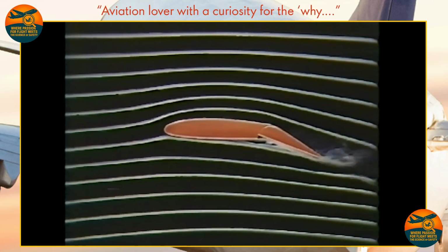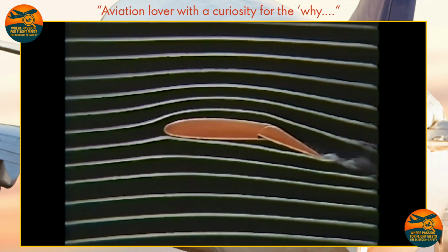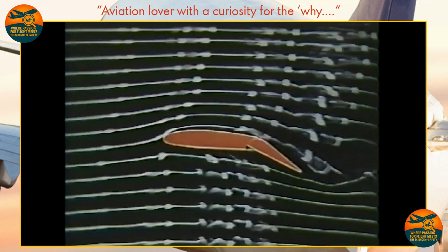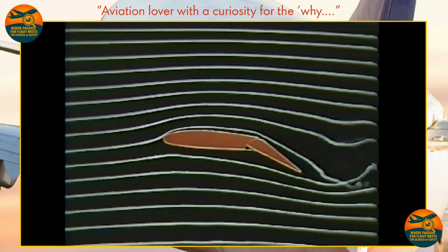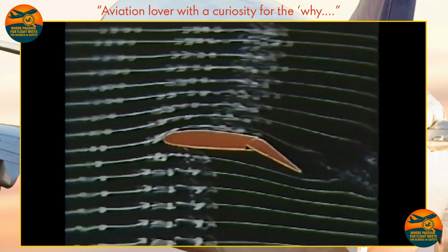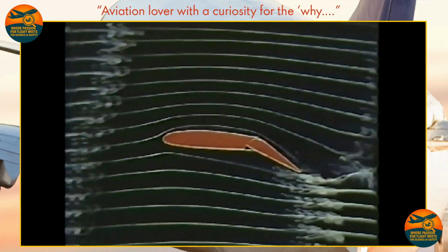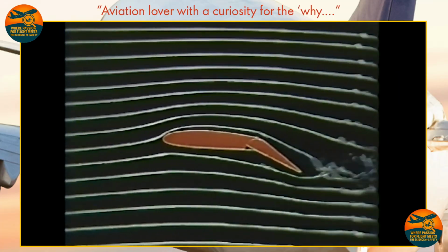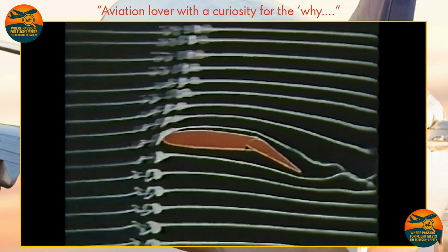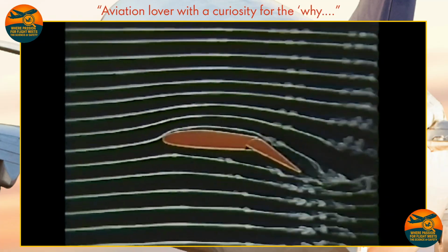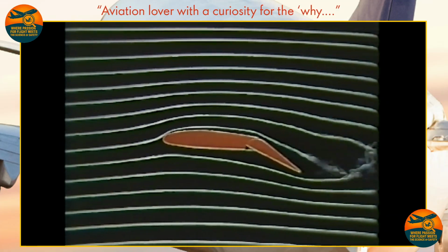The upper surface of the wing now has even greater curvature, and the airflow therefore moves even faster, while the obstruction caused by the flap below the wing tends to divert more air over the upper surface, where the pressure is now even lower. In this way, more lift is gained without any increase in flying speed.